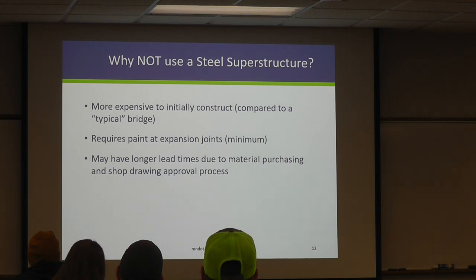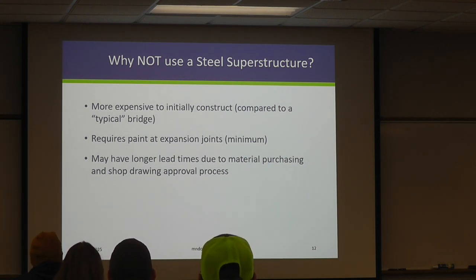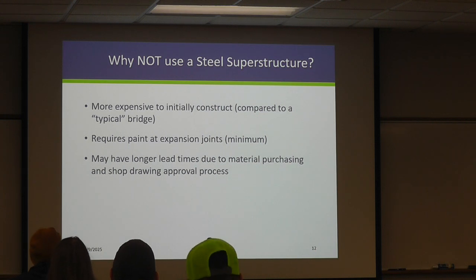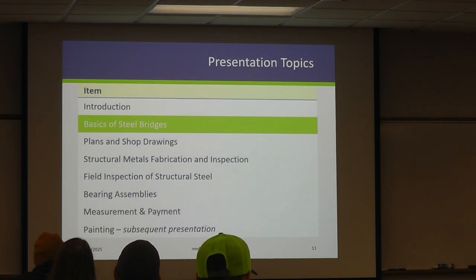And it can have longer lead times because with a steel beam, and we'll get into this a little bit later, the contractor is not going to buy any of the steel until everything's been detailed up through the shop drawing process and approval. So we'll talk about that because that can have project implications.